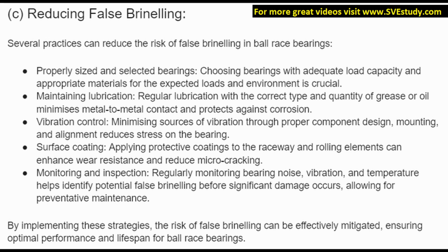2. Maintaining lubrication. Regular lubrication with the correct type and quantity of grease or oil minimizes metal to metal contact and protects against corrosion. 3. Vibration control. Minimizing sources of vibration through proper component design, mounting and alignment reduces stress on the bearing.